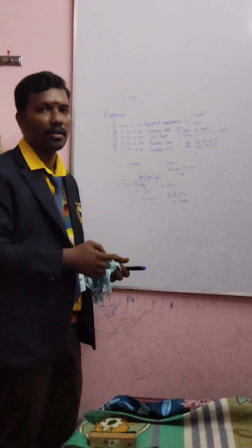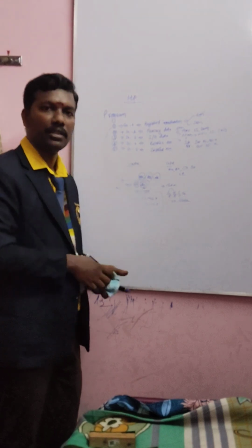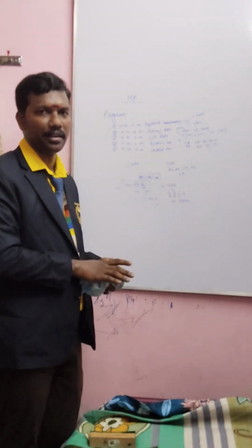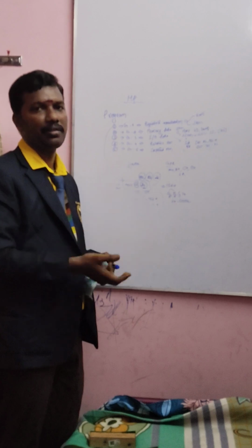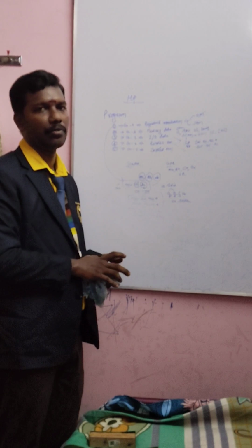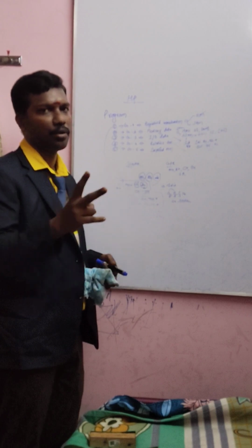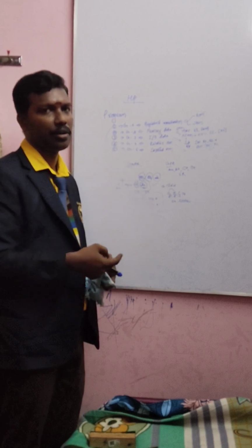Jump carry, jump. It means that suppose I'm going to do an addition operation. Okay, addition operation, two minimum data are needed. One is the augend and another one is the addend. If I'm doing addition, what type of result will come? Either the result will be with carry or without carry. If I have a carry, I need two locations. One for the sum result and another for the carry result. Two different locations will be used.